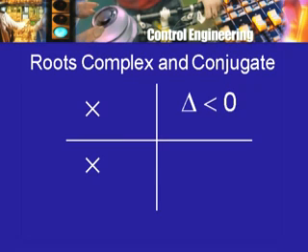Now what about the decision between these two? Either the roots are real and negative, or the roots are complex with negative real parts. Which one of the two will hold? Now this will depend on the discriminant of the quadratic, and therefore it will depend on the relative values of the various parameters of the motor.